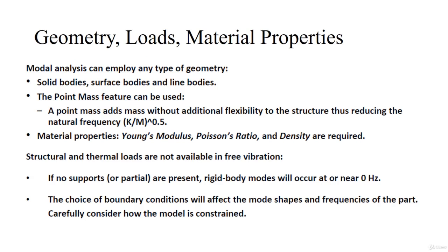Coming to the geometries, we can use solid bodies, surface bodies as well as line bodies in order to perform the modal analysis. In some cases, we can use the feature of point mass or distributed mass to add mass without adding any additional flexibility to the modal analysis.